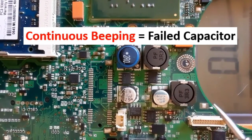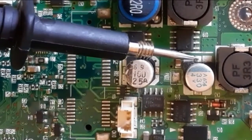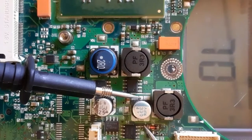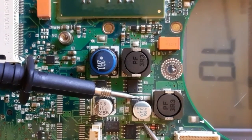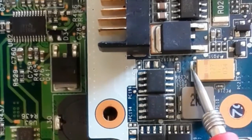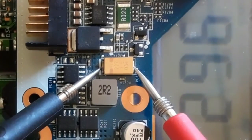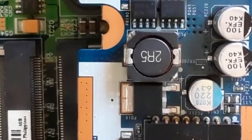So let's check this capacitor also. This is an electrolytic capacitor, so let's check it using the same working principle. We have the value in the multimeter increasing and decreasing, which means the capacitor charges and discharges, so this capacitor is good. Here also we have another tantalum capacitor. As you can see in the multimeter, the same, we have a reading that increases and decreases, which means this is a good capacitor.